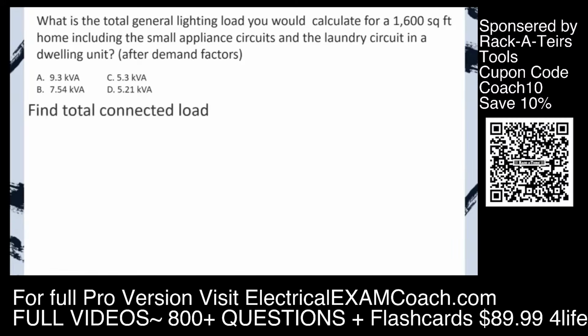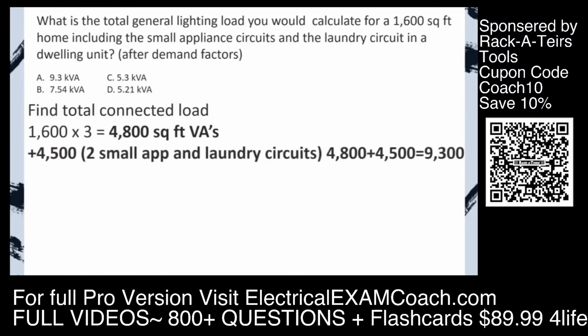Step 1, find our total connected load. We're going to take our 1,600 square foot multiplied by 3 VAs per square foot, and that equals 4,800 general square foot VAs. Now we need to tack on our 4,500 for our 2 small appliance and 1 laundry circuits.